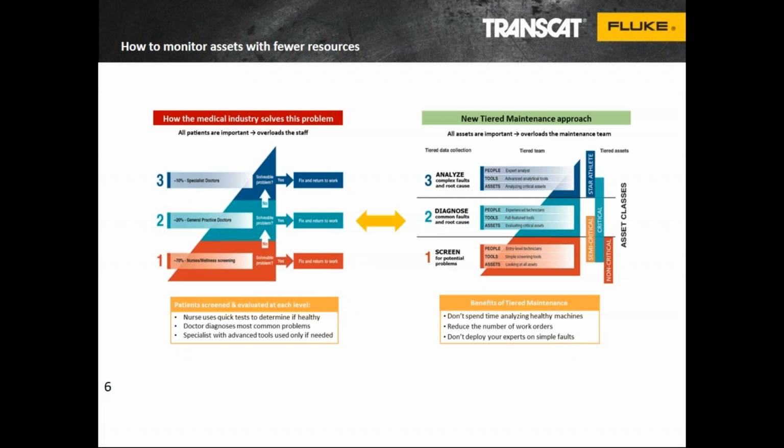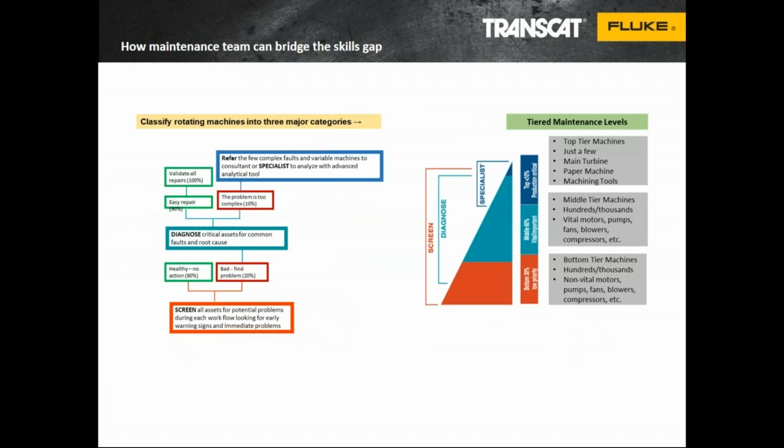But the point I'm trying to make, when we think about our maintenance program, is that we're not going to go in and see the specialist right from the very beginning. We're going to do some screening ahead of time. And this is one of the approaches that we can take in maintenance. We don't want to take the analysis tool out there to do screening work, where it's going to take someone's expertise, of which we may have limited resources, limited bandwidth and certain skills, for instance, thermography and vibration. We're not going to take this person with a skill set and this analytic tool to go out and do PMs. So we can take this approach to optimize our maintenance practices.